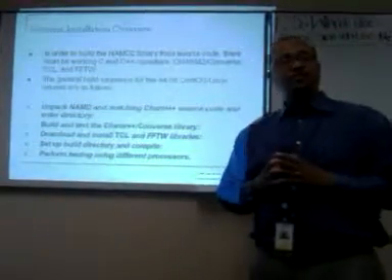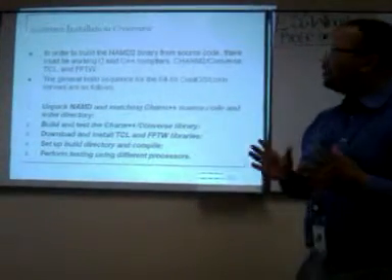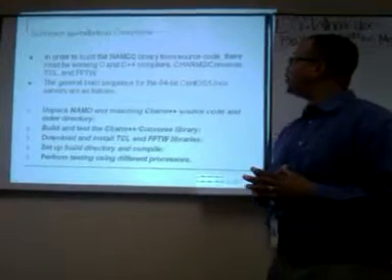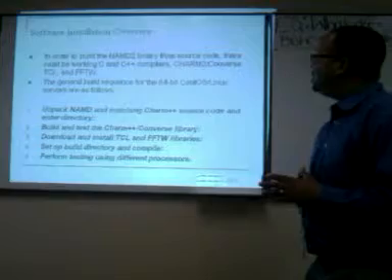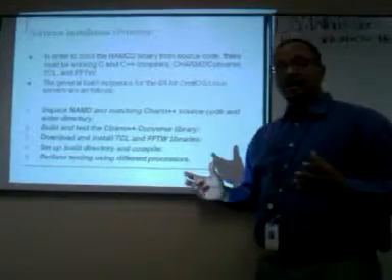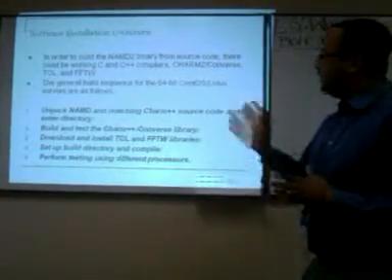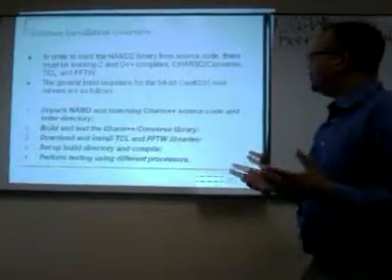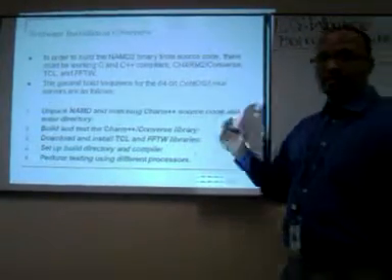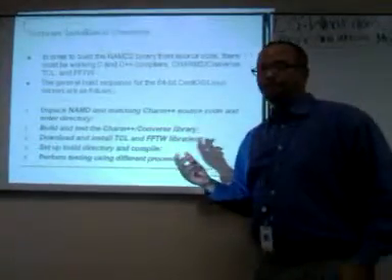Now we'll discuss the software installation. In order to build a NAMD binary from source code, there must be working C and C++ compilers, CHARM++, TCL, and FFTW. And here's the general build sequence, and we'll use a 64-bit CentOS Linux server, okay?